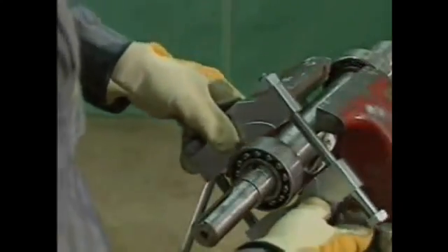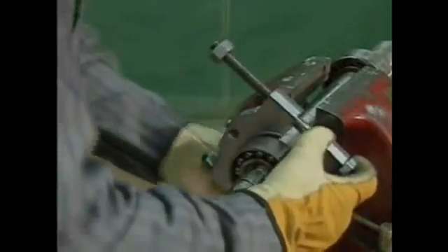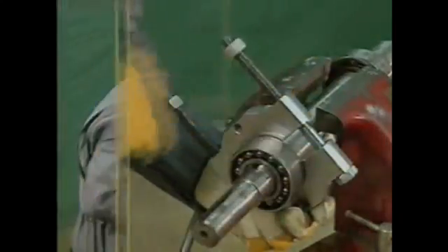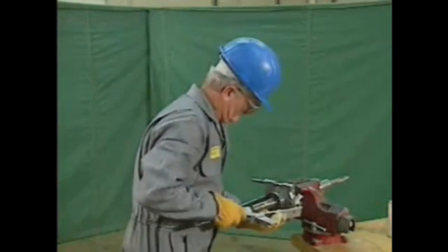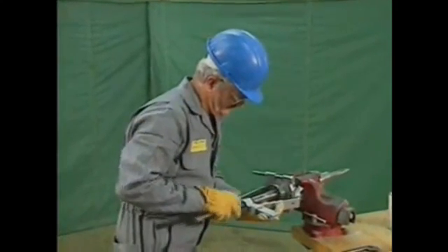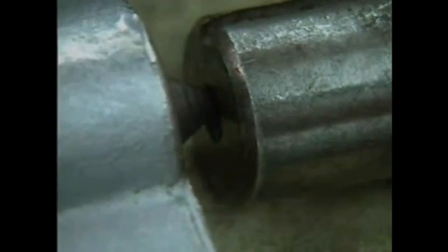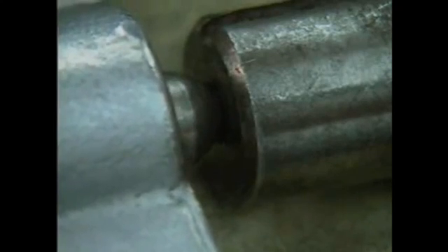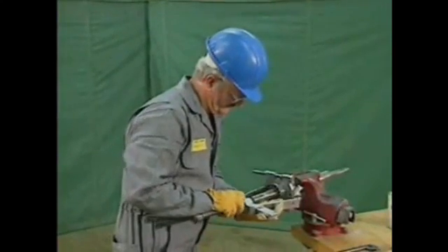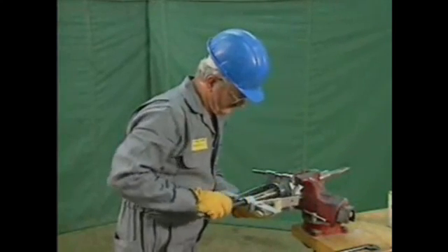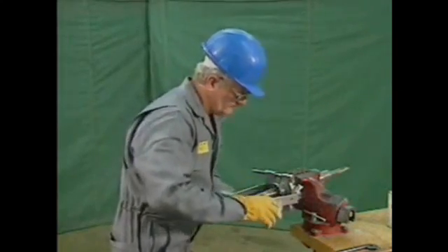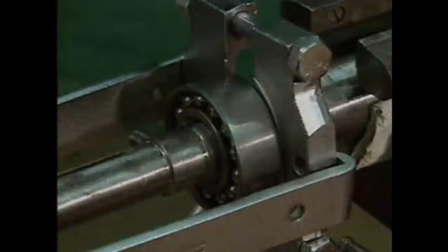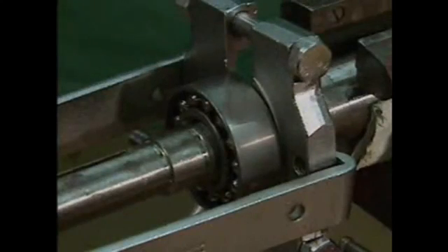Then he sets up the bearing puller jaws behind the bearing so that they rest loosely against the shaft. Next, the mechanic hooks the side rods behind the jaws. Then he makes certain that both rods are aligned correctly on the strong back. In this example, the mechanic places the lead screw into an alignment hole in the shaft. Then he tightens the lead screw. He checks the position of the jaws to make sure that they will only push against the inner ring. A good way to check the jaw position is to tighten the puller and then turn the bearing's outer ring. If the outer race can move freely, then the jaws are positioned correctly.